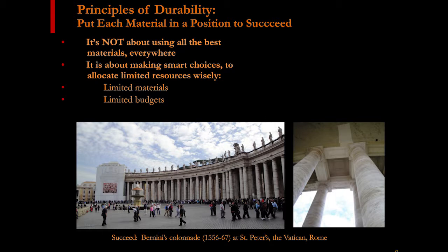But once you get inside the colonnade, and this is multiple bays and layers deep, this was a mock-up during the restoration. These are actually faux painted flat brick arches that are plastered over and then faux painted to look like travertine. You would never know from the ground, and I think from a durability standpoint and a budget and an aesthetic standpoint, he used the real stone in the right place, and then he used the fake stone in the right place too, and it's holding up really well. So he was smart about where to put the money in the budget.